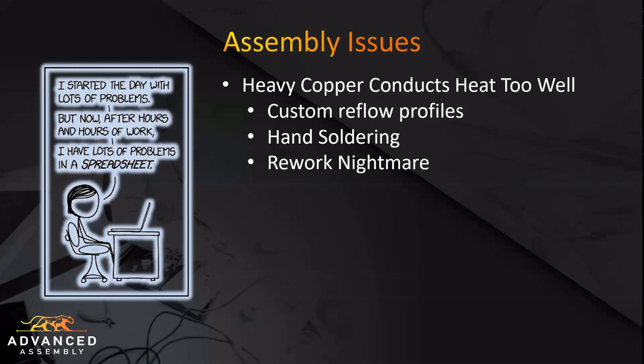So this becomes a problem, especially if you're using higher technology parts. BGAs require a certain amount of ball collapse. The QFN packages require a certain amount of fillet, and voiding is allowed. So most people would think that you just do a simple change to a profile or slow the conveyor belts down through the reflow oven, and you assume that's no problem, right?